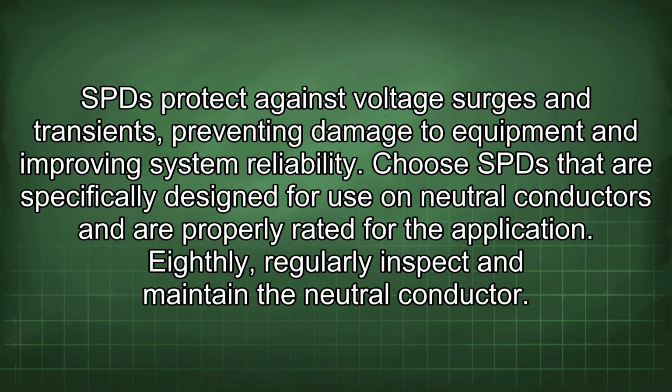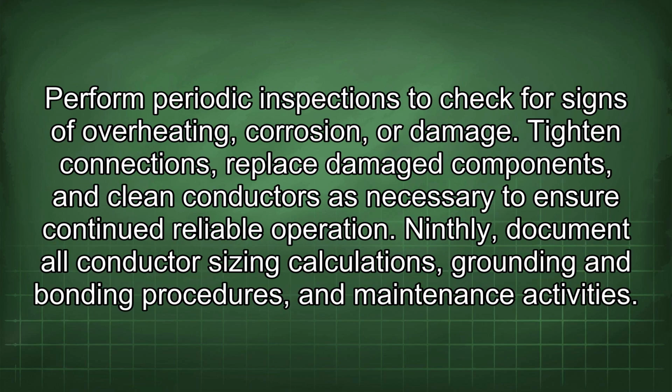Eighthly, regularly inspect and maintain the neutral conductor. Perform periodic inspections to check for signs of overheating, corrosion, or damage. Tighten connections, replace damaged components, and clean conductors as necessary to ensure continued reliable operation.